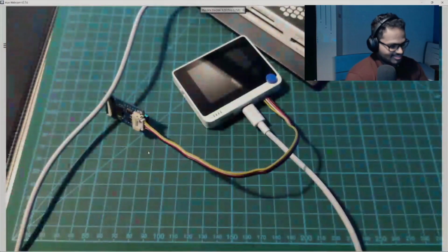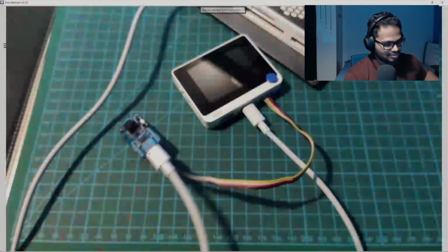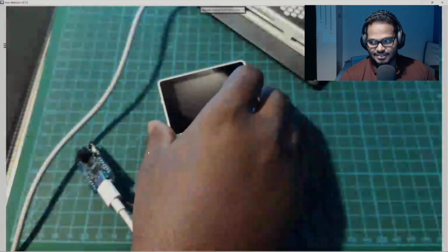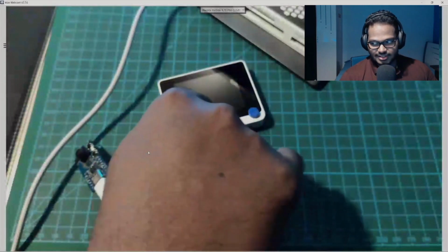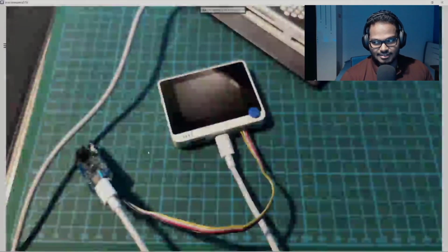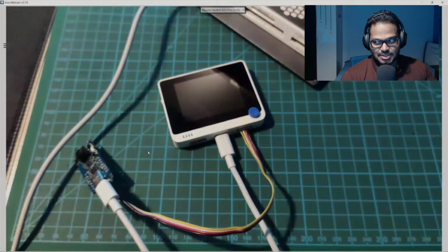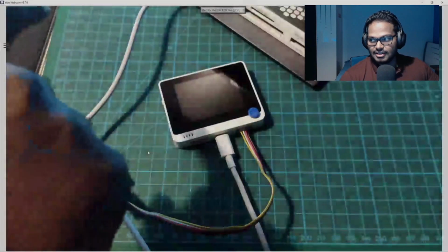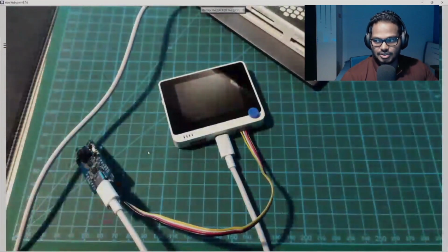and then we now connect this USB cable as well, USB-C cable, just to get a live video preview of the detection. Otherwise, it will only pass the detection details on the LCD, just like a person one detected. But what I'm going to show is that through the WebUSB protocol, it will pass the video output to the Google Chrome. So that's what we will do.